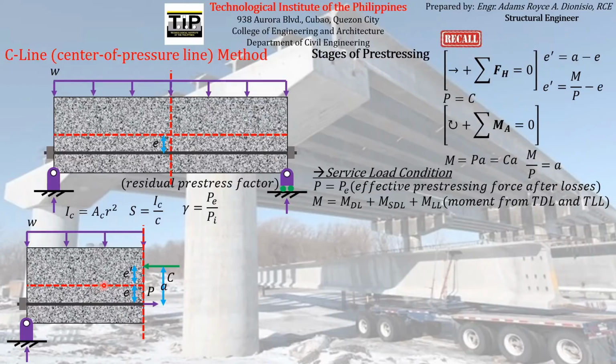And then after the concrete element bends upward, thereby producing camber, and forces itself to support its own weight, the location of the total compressive force C will slowly move upward as you apply a uniformly distributed load to the concrete element itself.